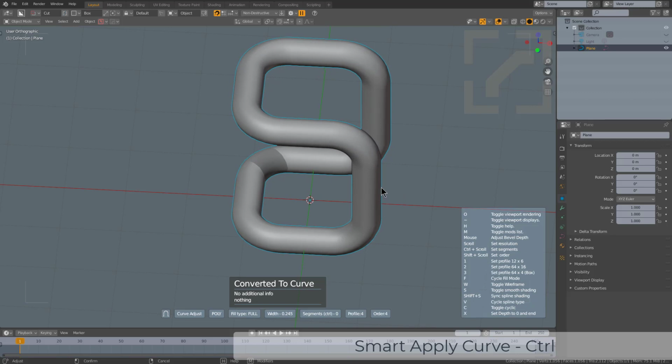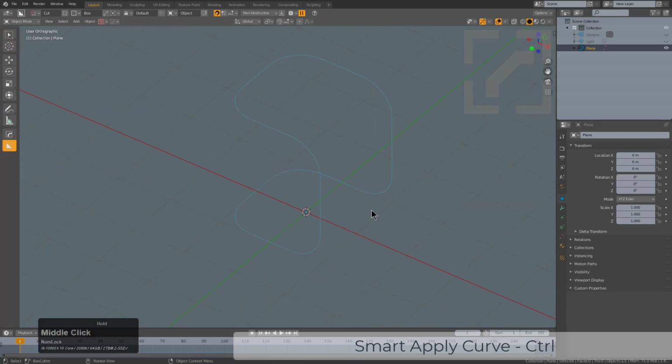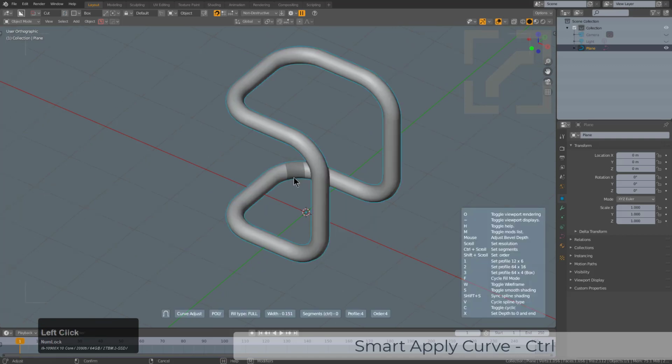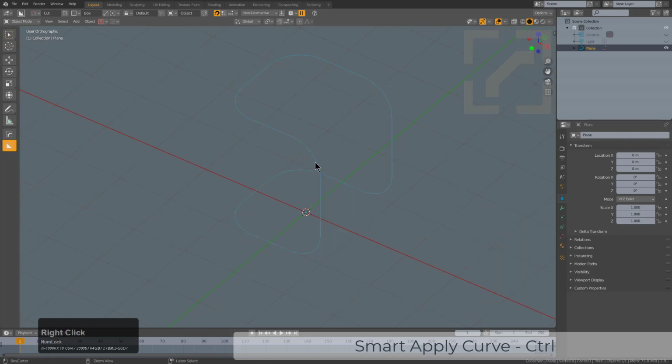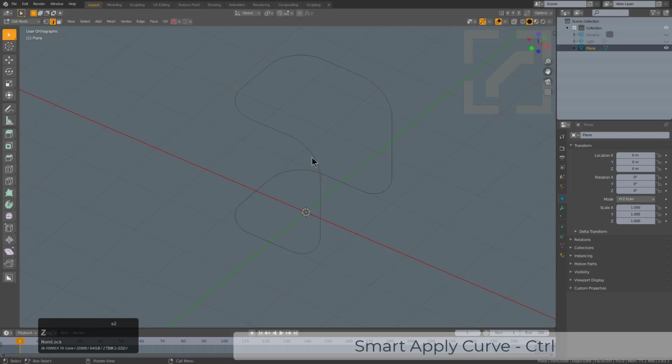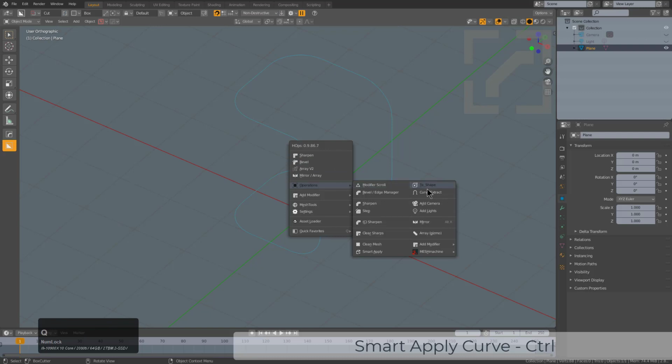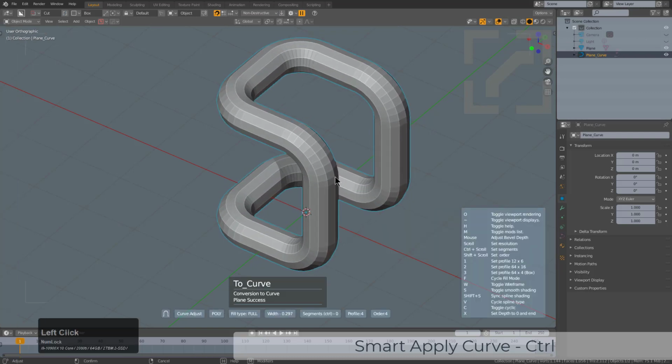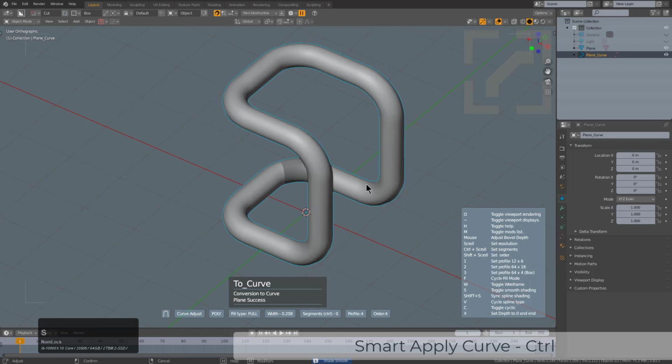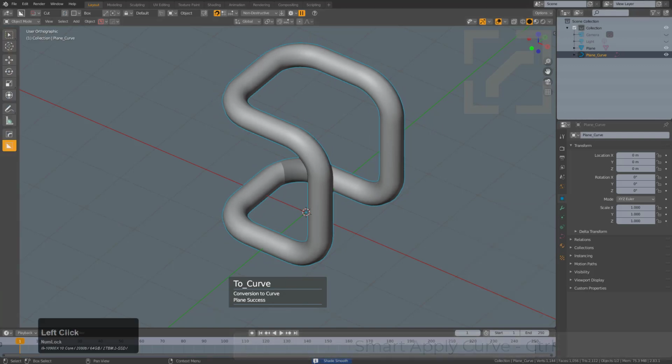However, I can tell you that we can right click cancel this, go back to right where we started, press Q, and just choose Adjust Curve. And now, actually, no, we don't need Adjust Curve. Let's pretend it was a mesh. So now we are dealing with a mesh. And if we go under Operations and we choose Curve Extract, you can actually just convert it to a curve flat out without any issue. And even press S to shade smooth if needed.